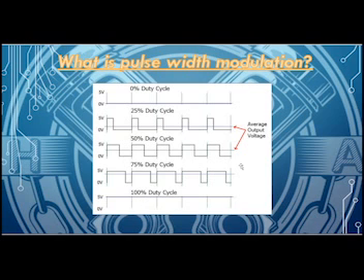The signal and the pulse that is being generated is known as a square wave. The reason for that is the shape that is being produced by it. Quite often with square waves, it would be a digital signal that's being created from any of the sensors around the vehicle. With an ABS sensor, if it had an IC chip, it would generate a digital signal, which means it will be more accurate and a lot more effective in terms of how fast it works.